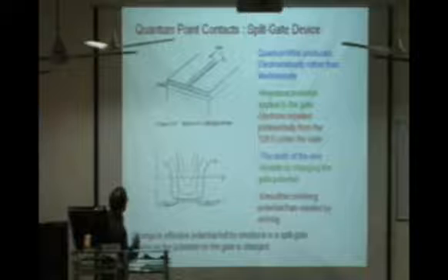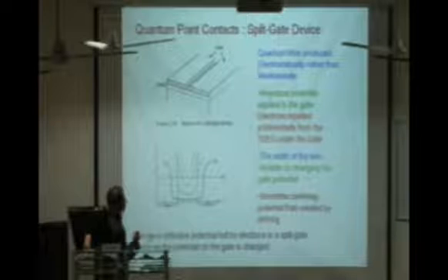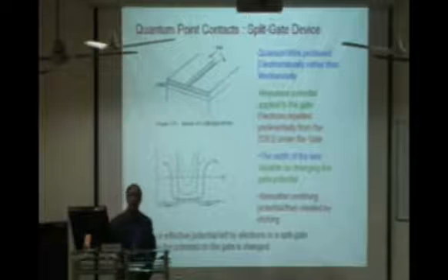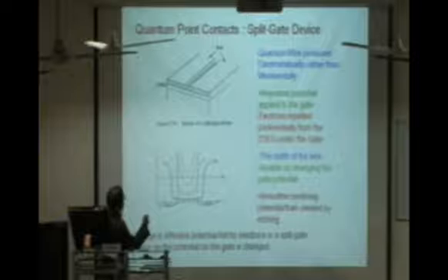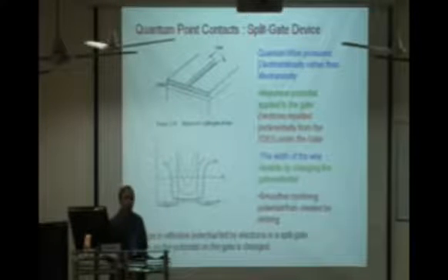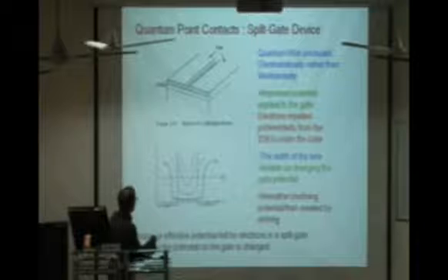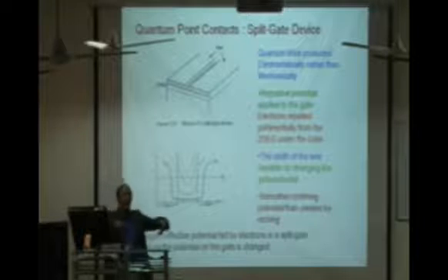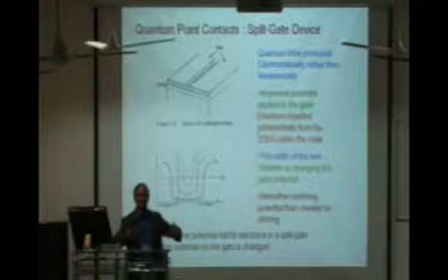In fact, this is some kind of structure called the MOSFET structure. So you put two gates, one gate is here and the other is the second gate, and below this you have some kind of quantum well, which we call a two-dimensional electron gas system. When you start biasing this gate, as you know, as you bias the gate in a semiconductor, depletion takes place just below the gate.